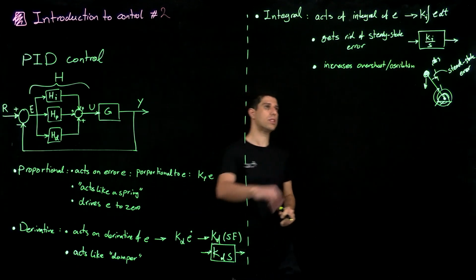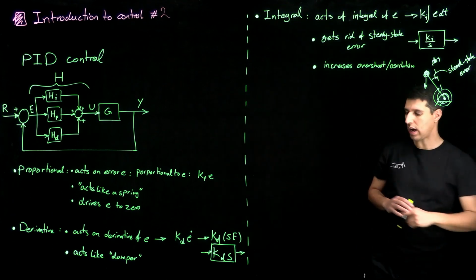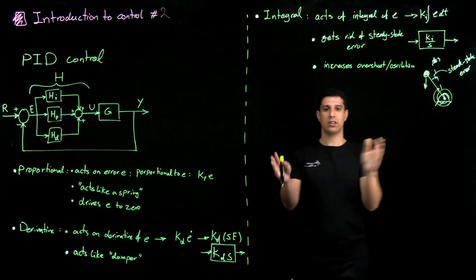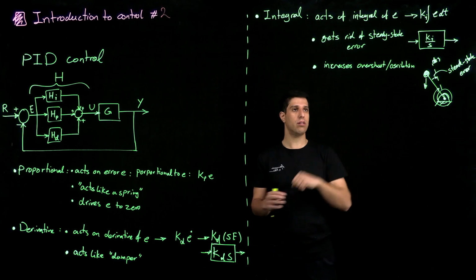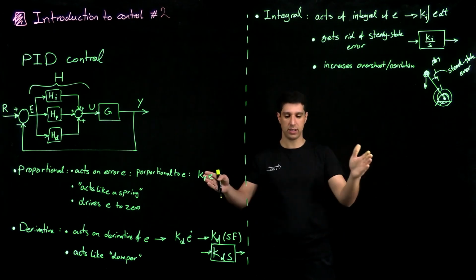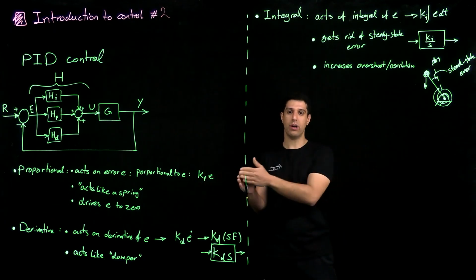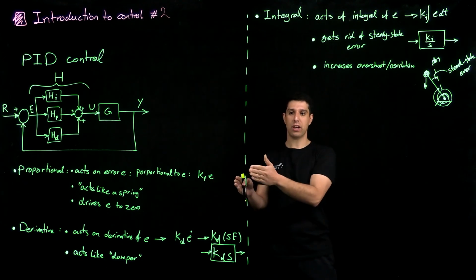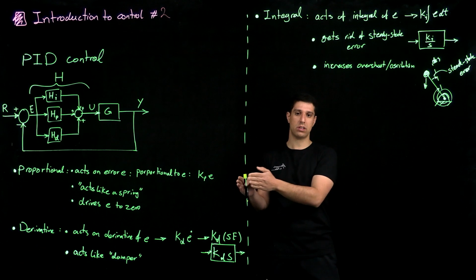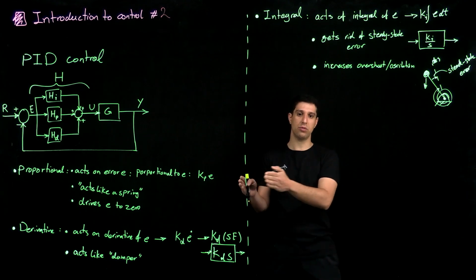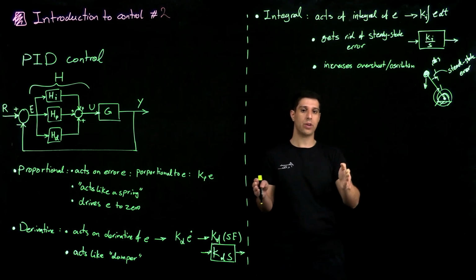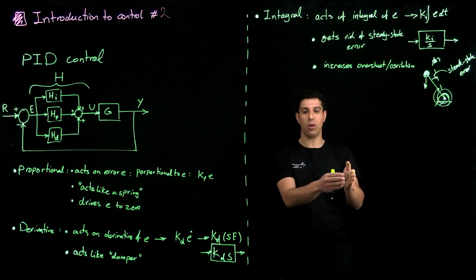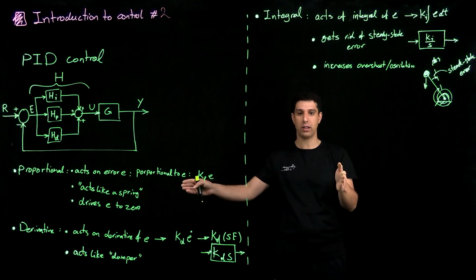And to see this effect, imagine you have a system. You have given it a reference. So at the beginning, there is no error. And all of a sudden, your reference jumps. So you start accumulating these errors, and your system starts to move forward. When you get there, you still have all this accumulated error from beforehand.